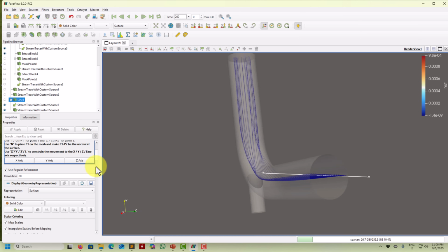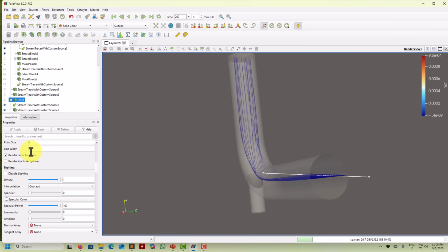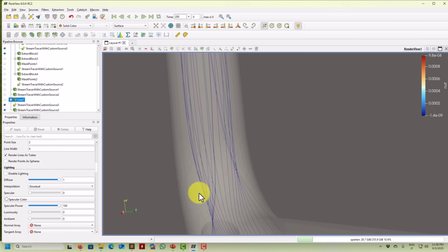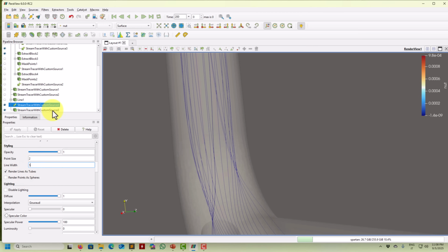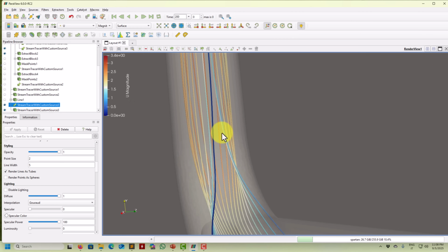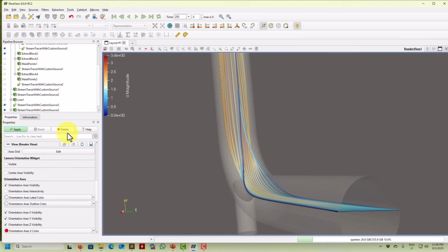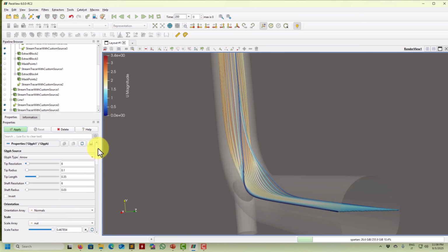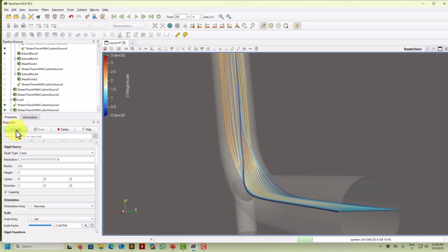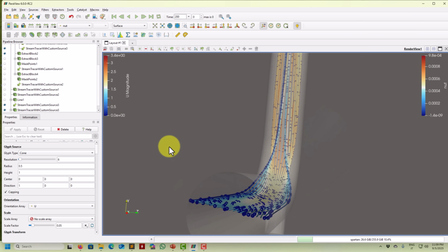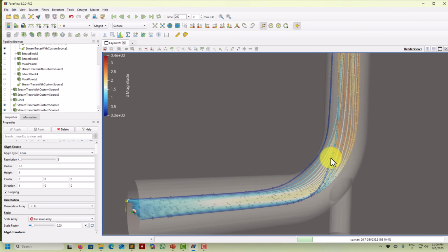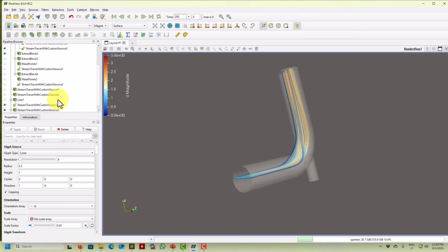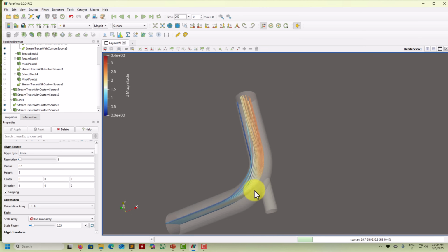And then you put stream tubes, which are a nice visualization. It's here, this one, stream tubes, and it is U velocity. And now let's also put glyph there. I want constant, I want velocity, I don't want scaling. So as you see, it's very mechanical. The moment you understand how to get that, it's quite straightforward. So there you go. Now you know the direction, and this is it. Very straightforward, applying all the tricks that we learned previously.